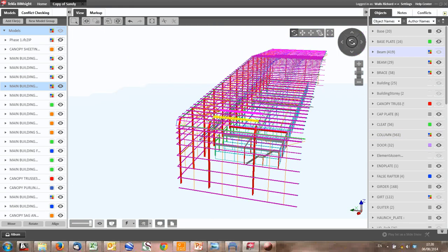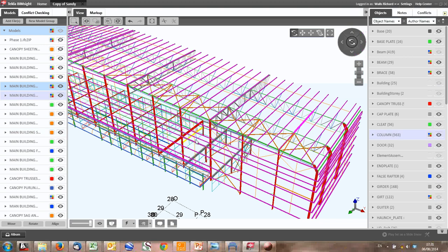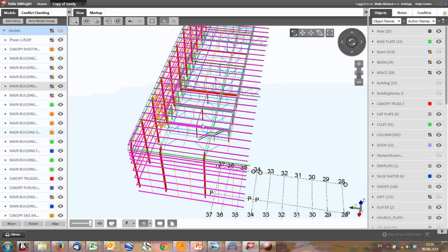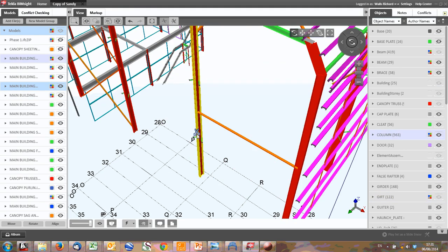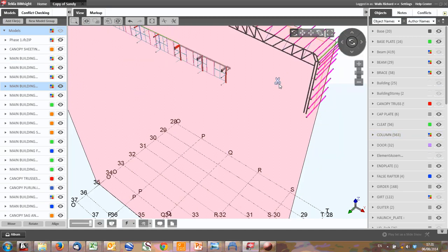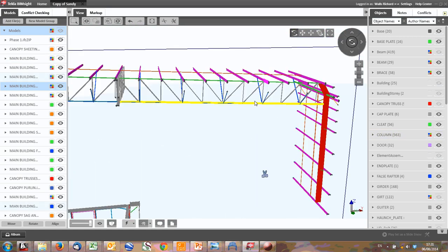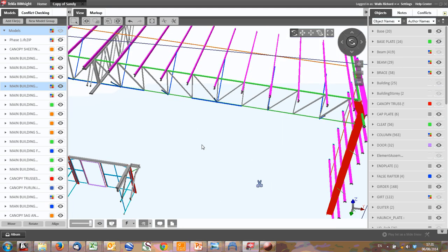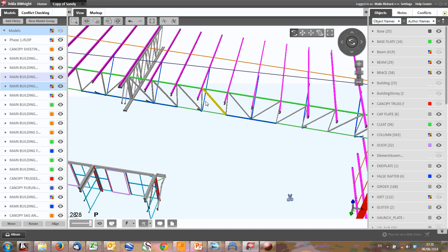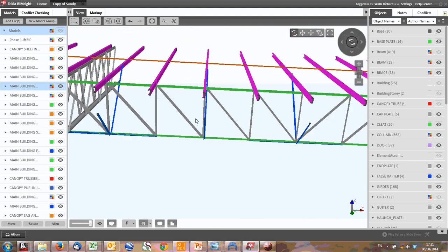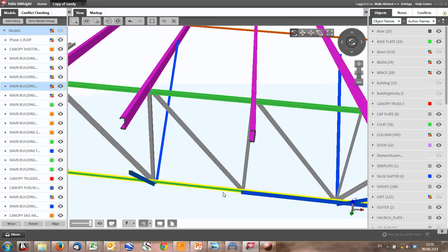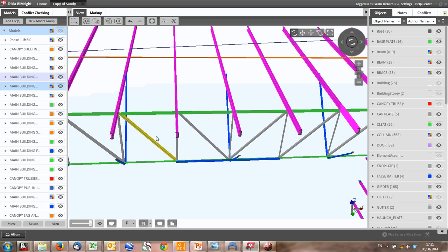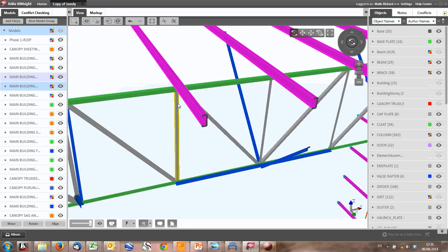A couple of final notes just about a few things if we're looking at the structure. Be very careful with trusses. Section through this thing. If I'm making you dizzy, my apologies, it keeps disappearing. Let's get a truss on its own. When you're designing this, have a look at effective lengths. If I am designing this truss, what is the effective length? How will it buckle? Well, easy. The angle will buckle from there to there, so according to the code, that should be 1 times the length. So people who design to the old code sometimes use 0.85 times the length. But anyway, there's various debates going on around that.